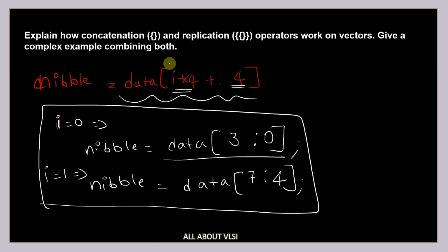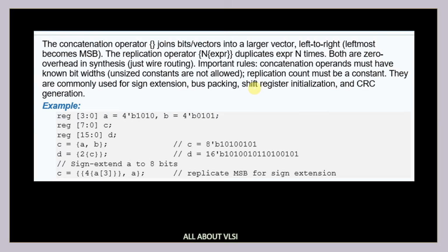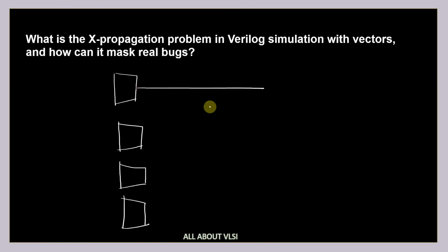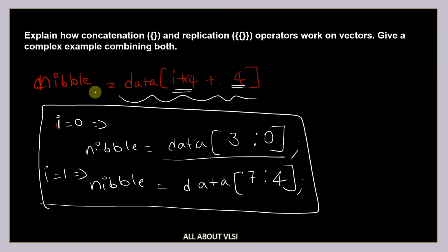Now what it is going to do is, since the width is constant over here, the compiler or the synthesizer is going to take 4 multiplexers like this. Since the width is constant over here, right? So the compiler or the synthesizer is going to yield 4 multiplexers when we use this particular syntax. Now, what is going to happen again?